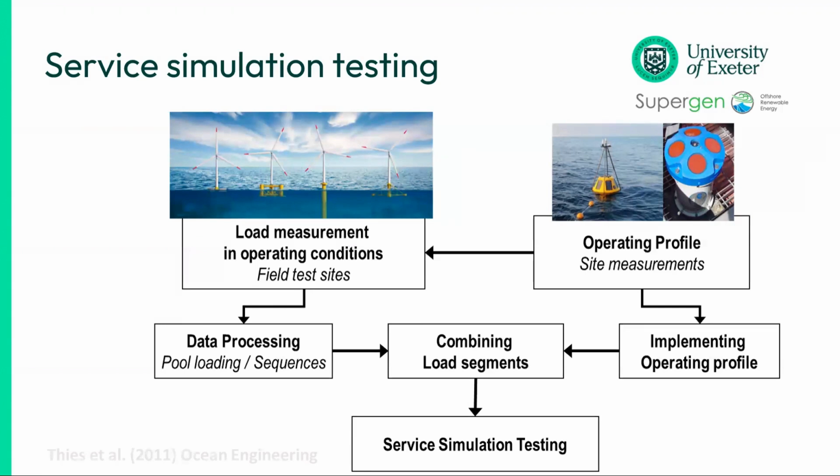And if you can measure those either in the field or capture them numerically, you can look at the different operating profiles and identify load segments that cause you fatigue damage over time, and you can collect them up and sequence them in a service simulation test, so that you have a physical test of what you think that cable or the mooring system, if you're testing other systems, what those components would have to withstand in the field. So you're trying to replicate that as much as possible before you go out to site.